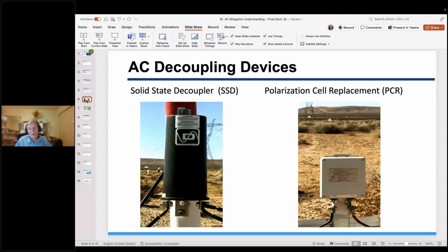And remember, a fault could be, most of the time, in microseconds. But if it's a fault from the power lines touching each other, then it's going to be in milliseconds. So we got two different faults, one from lightning and one from, how could I say, poor maintenance or design of the power lines. So we got those issues to think about.